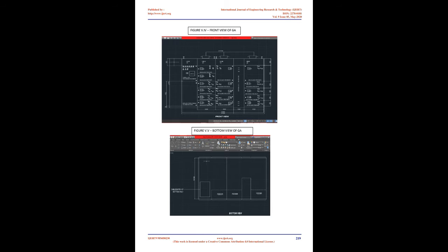3. Phase advancers. They are used to improve the power factor of induction motors. Due to the fact that the stator winding draws exciting current which lags behind the supply voltage by 90 degrees, induction motors have a low power factor. If the exciting ampere turns can be supplied from some other AC source, then the stator winding will be relieved of exciting current and the power factor of the motor can be improved. This job is accomplished by the phase advancer, which is simply an AC exciter.